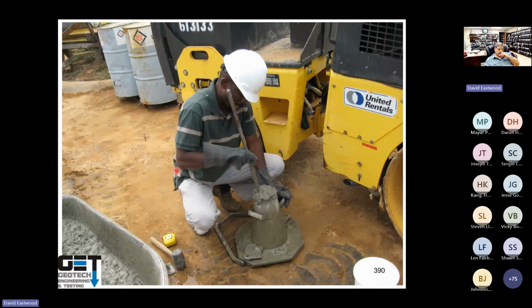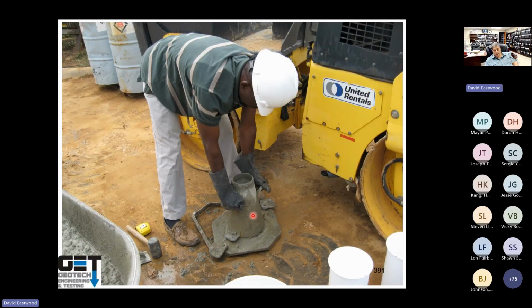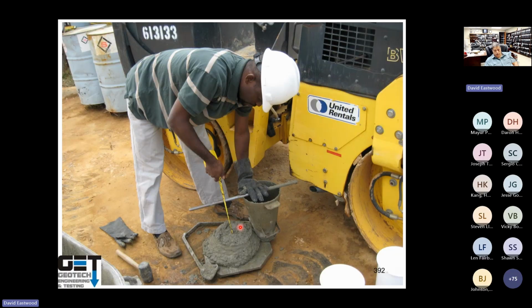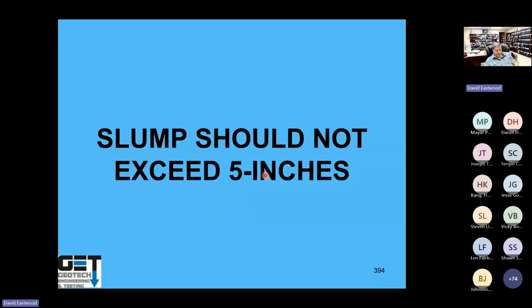Slump test: your concrete slump should be 4 inches. Open counting allows 2 inches past the 4 inches. You can go up to about 6 inches. You put the concrete in this cone in 3 layers and 25 rods per layer. Pull up the cone. You measure the slump from here to here. It should not exceed 4 or 5 inches. If it's more than 5 inches, you reject it. Some counties allow up to 6 inches. Slump should not exceed 5 inches, but again, look at the specs for that county.